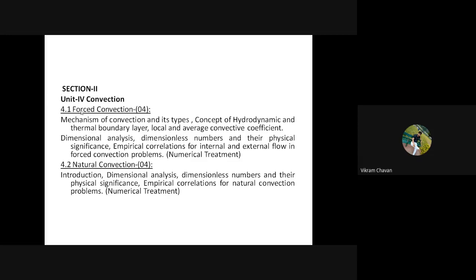So we are using an external device to increase the heat transfer rate. That is nothing but forced convection. Convection we have defined earlier: transferring heat by using a medium, any fluid medium, is considered convection. And forced convection means if you are using any external device to force the medium over the object, then the heat transfer from the object will be considered forced convection.